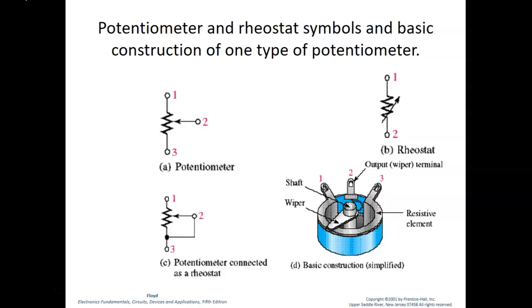So this is one of the potentiometers you will be playing with in lab. You can see I've got 3 wires to it. It's got a dial to it. So as I move it one way, depending upon which lead I'm looking at, 2 and I'm either looking at 3 or 1, as I move it, my resistance values will change depending upon where this wiper is connected between that resistance. Does that make sense?